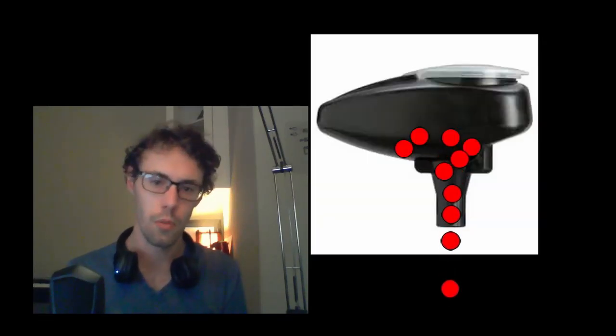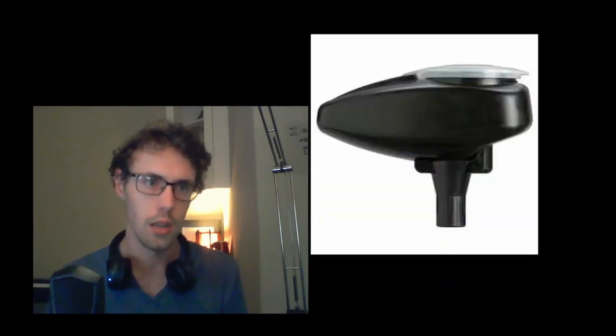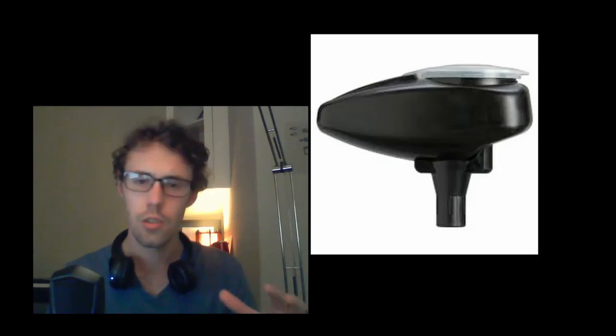But anyway, there are a lot of things that can be modeled as part of the system using a state space controller, such as the effect that temperature has on your bearings, the change in weight from the paintball hopper, and a lot of the other small nonlinearities that you can model into the system so that you can get a really smart controller that knows exactly how much torque to apply in every situation. But we're not docking with the space station, so we're just going to use a PID.